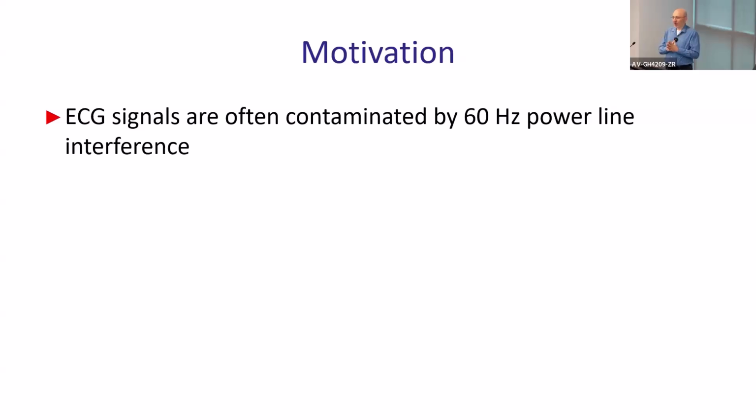So we have a lot of problems with cleaning that type of signals, and especially all kinds of problems with outside power line noise, which is 60 Hertz and affects all kinds of channels unexpectedly. You don't know what phase you have to that signal, what amplitude you have to that kind of signal, and so on. So it might be a problem, right?